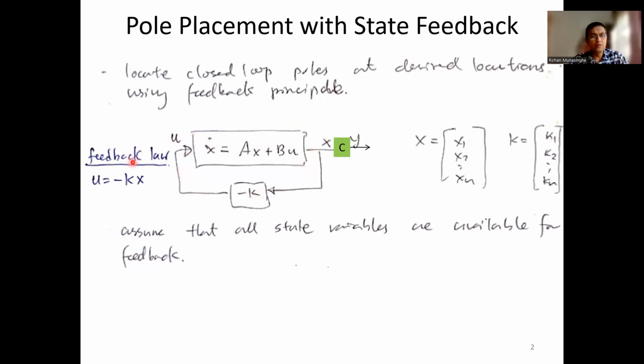So the control signal here is actually the inversion of state variables. Now, this is what you call the control law. You need to have some sort of criterion, some policy, for how to generate the control signal. If you look at PID, it has a very clear policy. It tells you, if the error is this much, the rate of change this much, accumulated this much, combine them together through these weights and add them together, that is the control signal. Some policy.